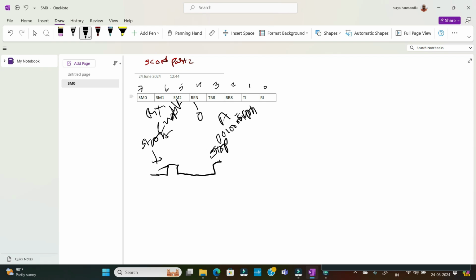What indicates this for us is the SBUF register, the serial buffer register. This is the only register available for both transmission and data reception. So both transmission and reception cannot happen at a time. That means these are mutually exclusive events.